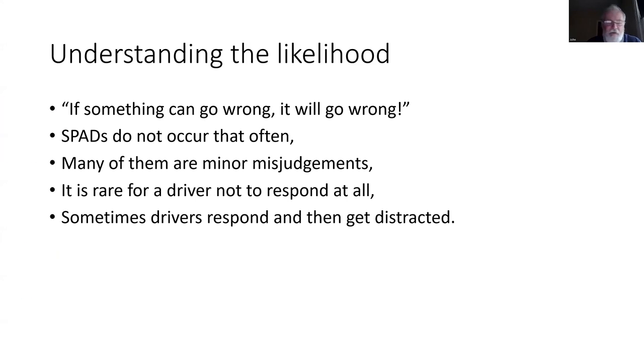If one looks at the accident that occurred at Salisbury, from reading the accident report, it appears that the driver did see the first caution. However, knowing that that was a very long distance from the red signal, and knowing that normally they didn't need to brake until a later point, they continued at a higher speed, looking for that braking trigger, which they then missed. And when they did realise they needed to brake, it was too late, and a SPAD occurred, and unfortunately led to a collision.